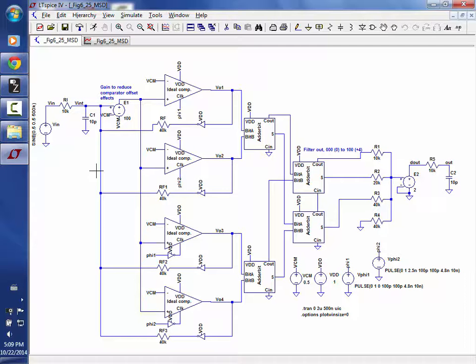I'm asking a trivial question. How do I determine that? Yeah, differentiate. Put it in a differentiator, then I get my edge. It comes down, then I get my next edge. Well, then I know where the edges are, and I can set up my timing information. There are other things you can do with it once it's digital. If I need more gain, well, you can gain it up. I can adjust the amplitudes of the signals that I'm feeding back to the input. Okay, so life is good.